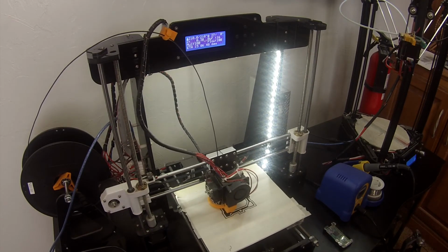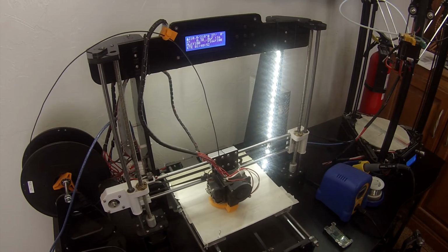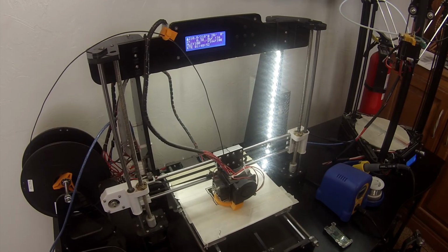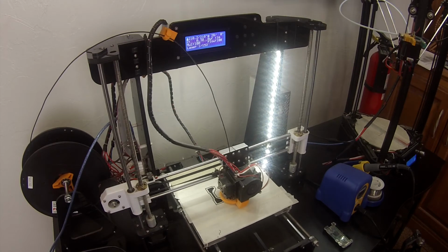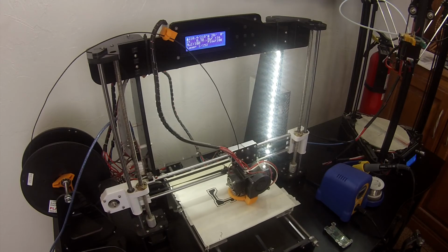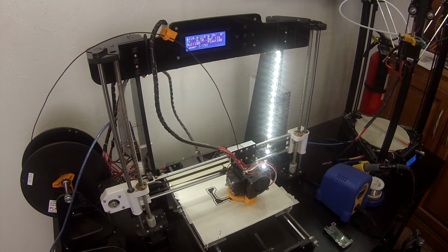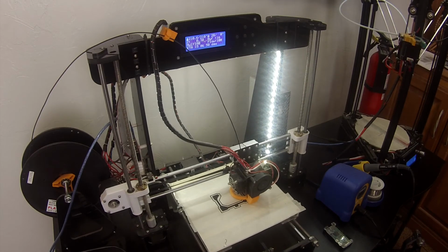Already at this point, if the print did not go well, I'd have so much plastic down on the masking tape that it'd probably be best to just go ahead and replace that masking tape region. I print on tape. You'll find lots of other recommendations. There are some really nice build surfaces. Some are magnetically mounted, some of them clamped down. There's some really great stuff out there available. But for me, tape is cheap. It's kind of a safety feature because if I just get it really stuck to the tape, then at least I can peel the tape up off the bed and I don't risk fusing something to the aluminum print bed of my printer. And overall, I've used it for several years and it works quite nicely.